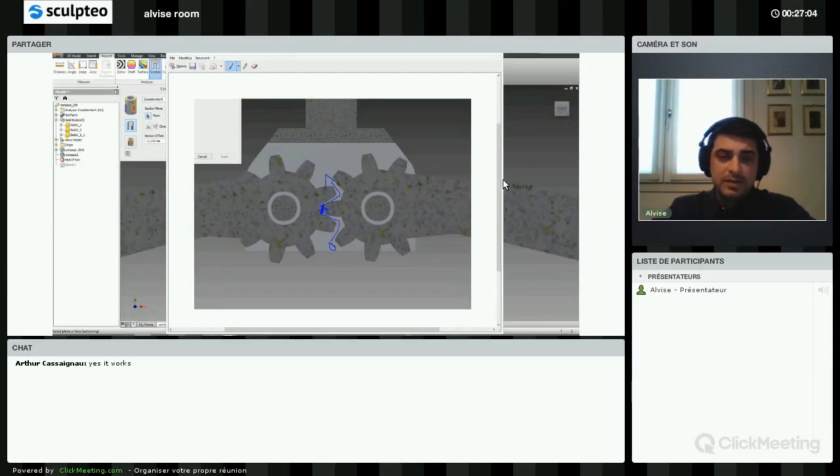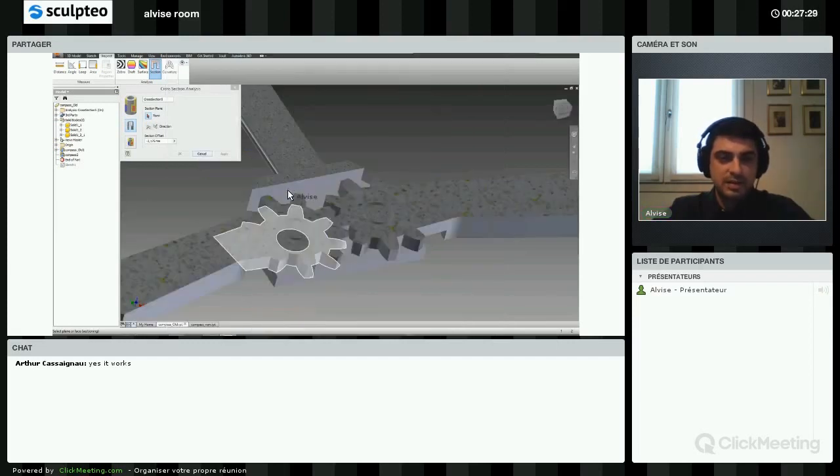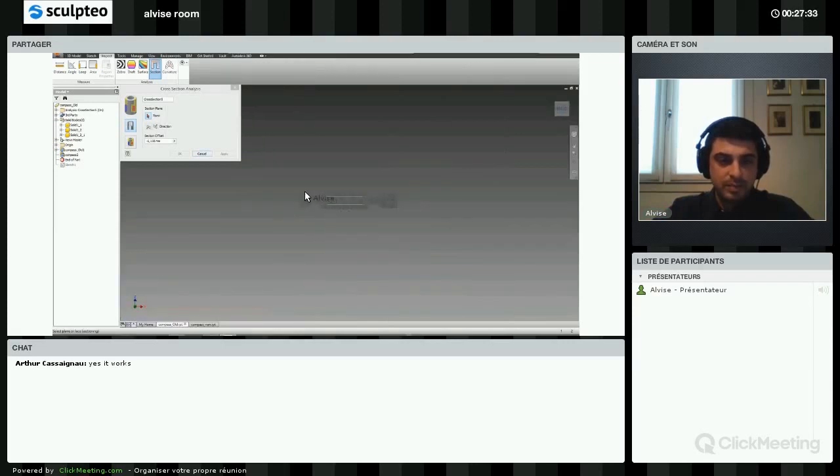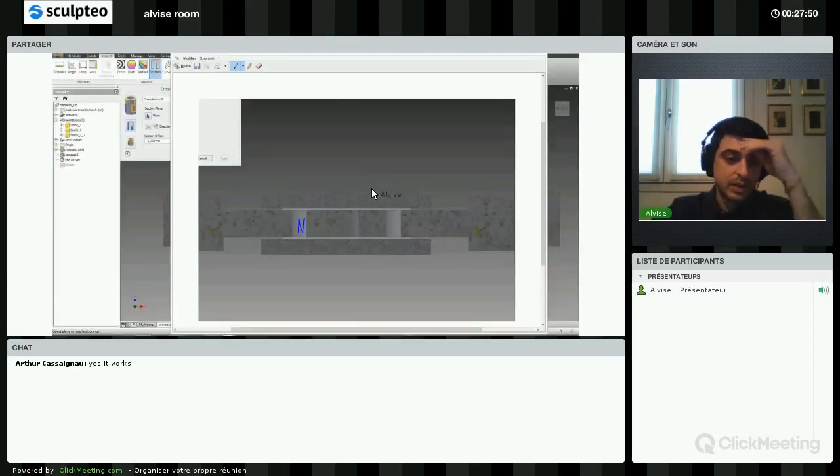Here I have a straight escape path, so no problem here. Let's check the second section in the other axis, and apply it here. Also in this second axis, I see I have no escape path, and all the powder will get stuck in here. There are straight paths here and here, but even with the pressure air or sandblasting machines that our technicians are using, this powder will just get stuck in this area and make the escape path not so straight.